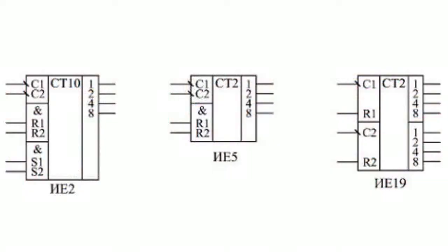The more bits a counter has, the more time it takes to complete switching of all bits. This imposes severe restrictions on the input signal frequency. If the number of the counter bits is increased, for example, by half, the maximum permissible frequency of this input signal will be automatically reduced by half.